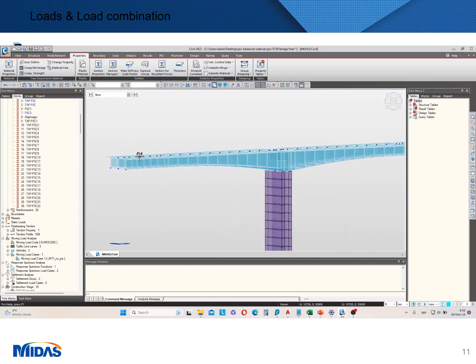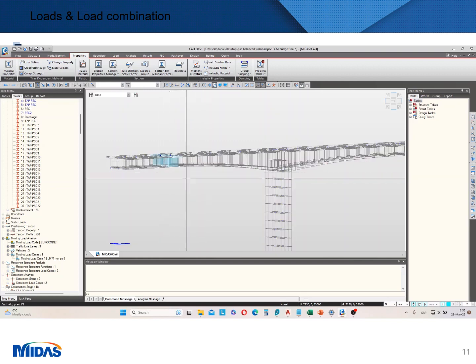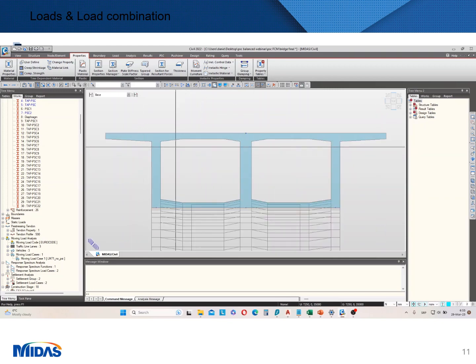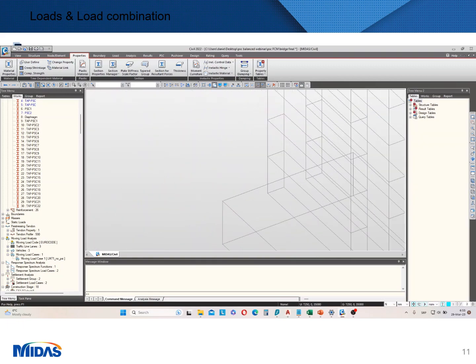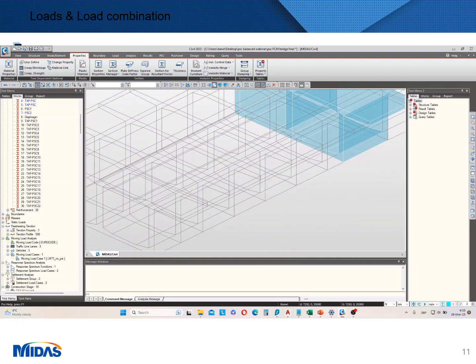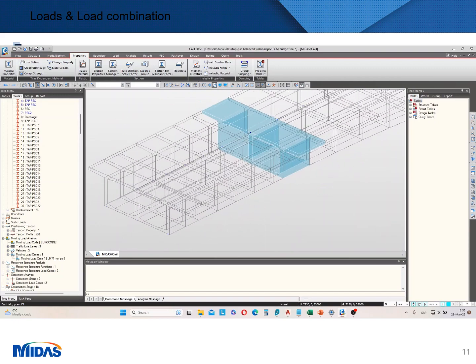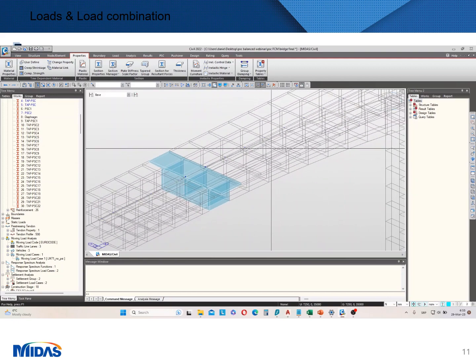If you choose any of the elements you can actually isolate it. You click on activate, or I prefer to use the shortcut F2. Here you can see how it looks. If you don't like the wireframe display, you can turn it off too.